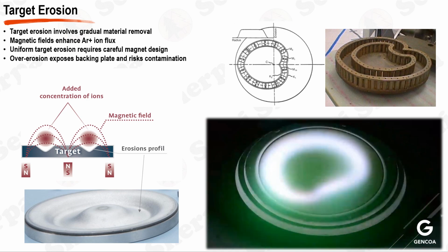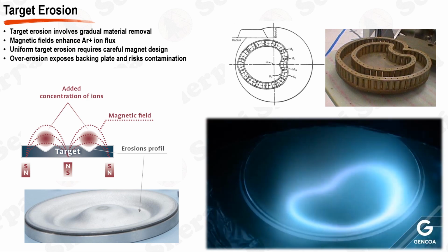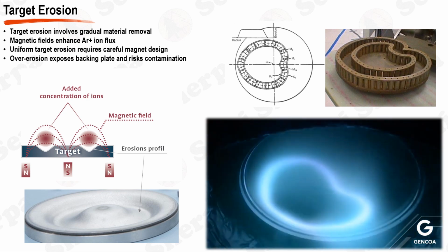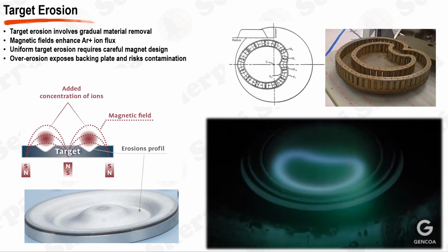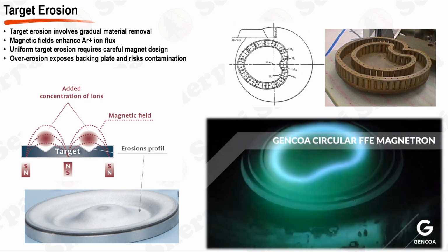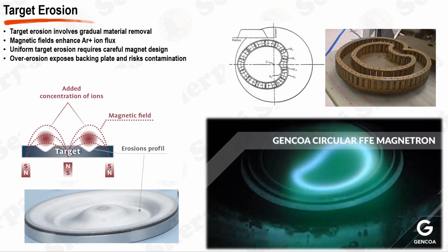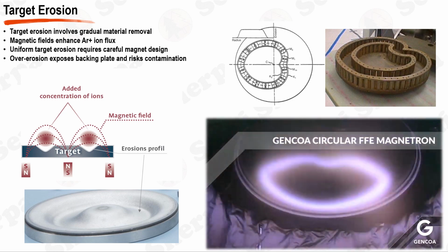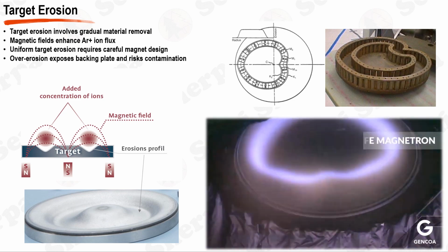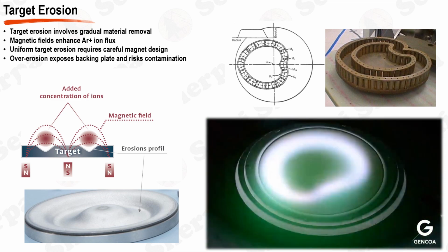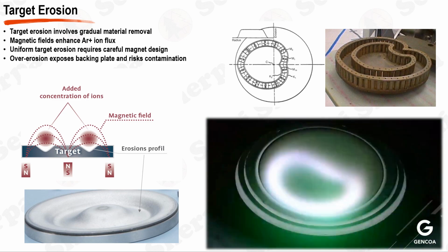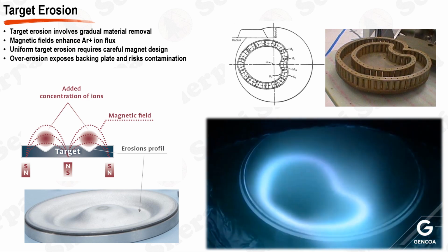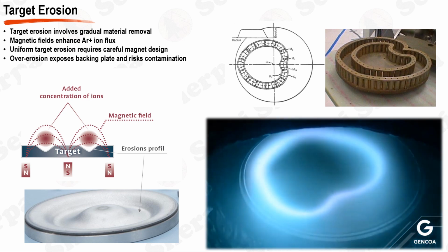The design of the magnetic field is crucial in achieving uniform target erosion. The field design can be shaped in various ways, such as a rotating design, a heart-shaped design, a spiral design, or Applied Materials' patented universal magnet motion, UMM. These designs ensure that the ion bombardment is evenly distributed across the target, preventing any specific area from being eroded excessively, thus maximizing the target's lifespan.